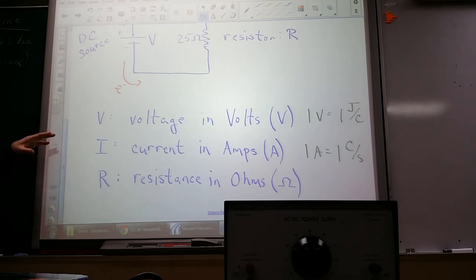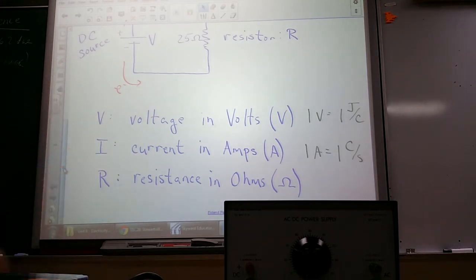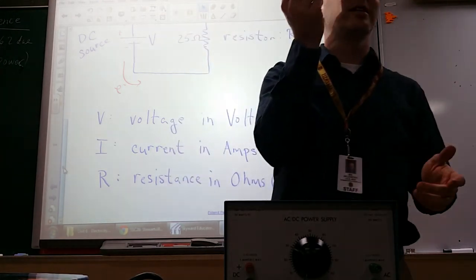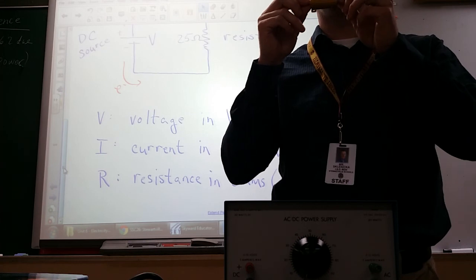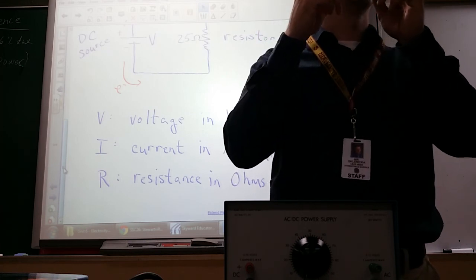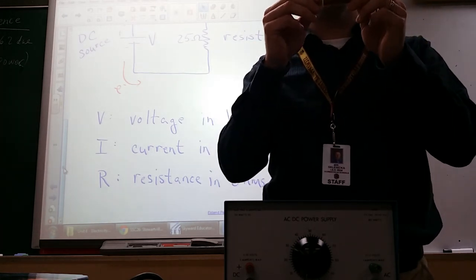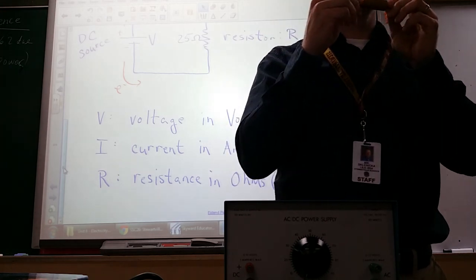Okay, so we're going to be measuring 2 of these things. We'll be using resistors for this lab. I've got a couple boxes of them over here. I'd suggest using the larger ones only because they won't heat up very quickly. So this is one example. This one is actually, ironically, used in order to heat things, but not with the amount of current or the amount of time that we'll be using it for. It's very big so that any heat that's building up will spread out throughout it and be given off little by little. Every resistor has its value recorded on it.